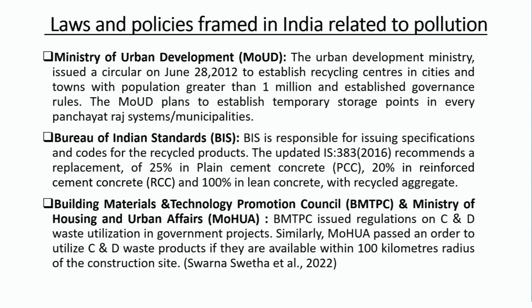Bureau of Indian Standards. BIS is responsible for issuing specifications and codes for recycled products. The updated IS, Indian Standard 383, which was issued in 2016, recommends a replacement of 25% in plain cement concrete, that is PCC, 20% in reinforced cement concrete, that is RCC, and 100% in lean concrete with recycled aggregate.